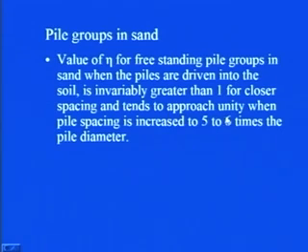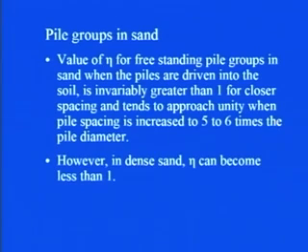However, it will approach unity when you increase the spacing of the piles to 5 to 6 times the pile diameter. In dense sand, eta can be less than 1. So, you have to keep in mind that in clay it was the vice versa case. That distinction you must keep in your mind.